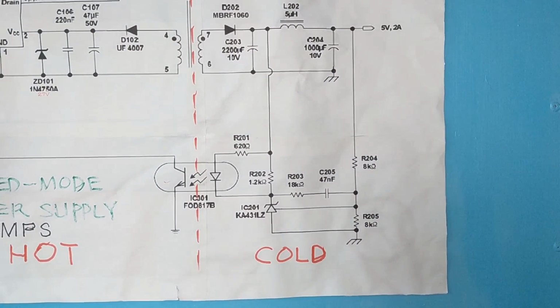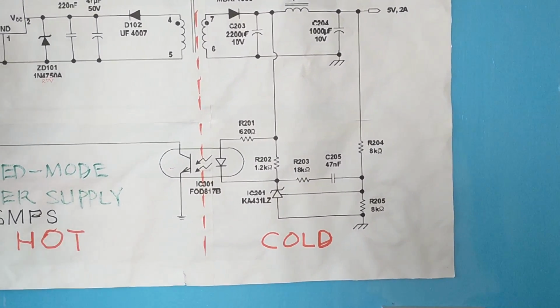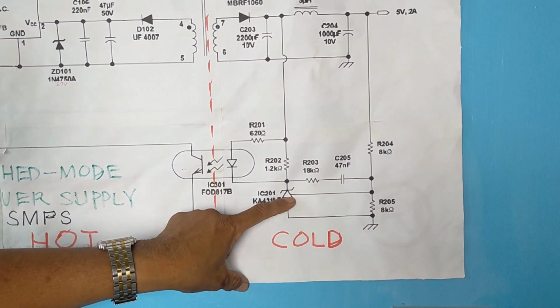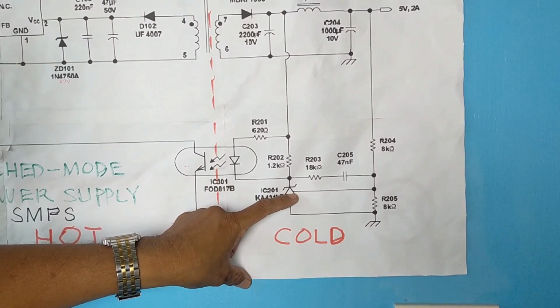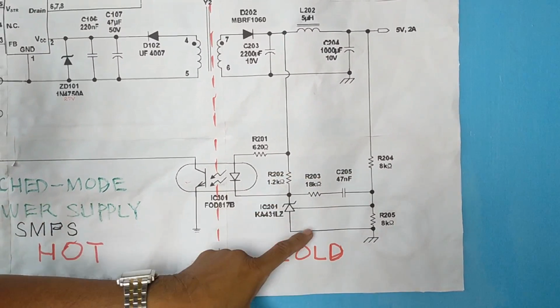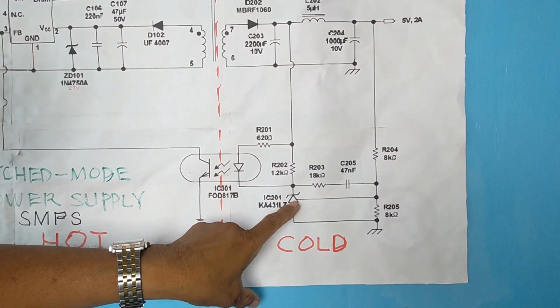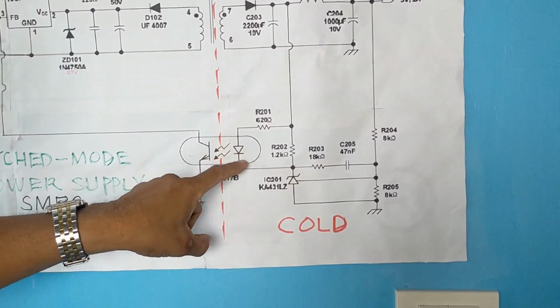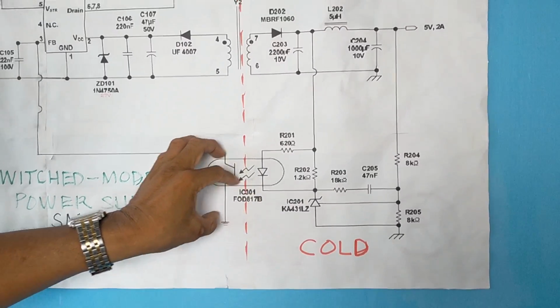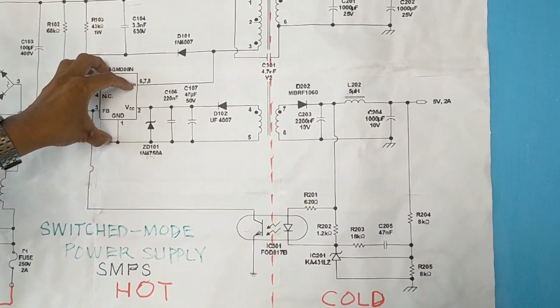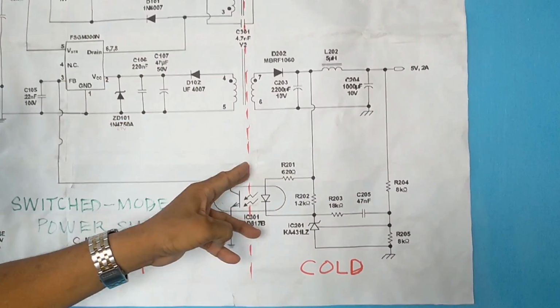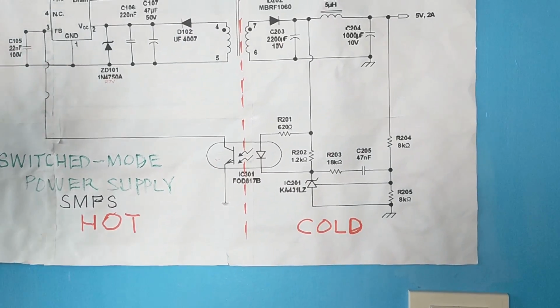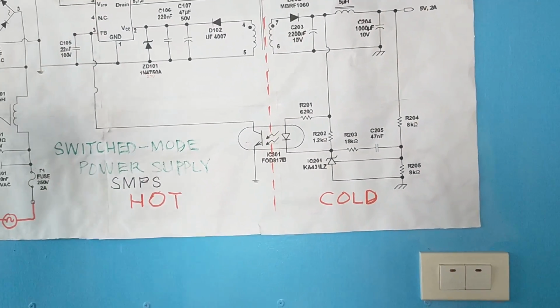There's a difference again, negative 0.5. Because this is 2 volts, then this is 2.5 volts. The reference voltage is much bigger. So, negative feedback will be sensed by this sensor here, then submitted to the control voltage IC through the optocoupler. Okay, it goes like this, class.